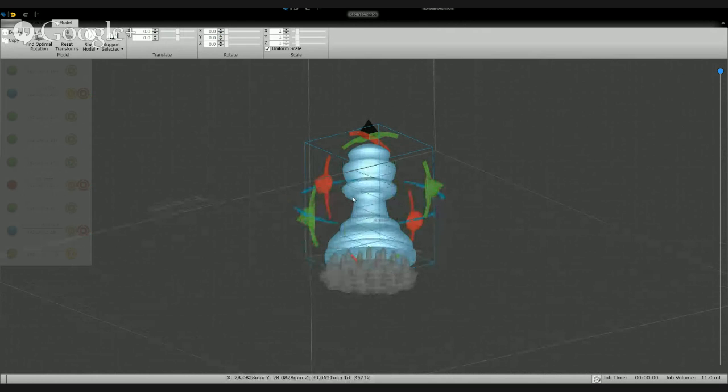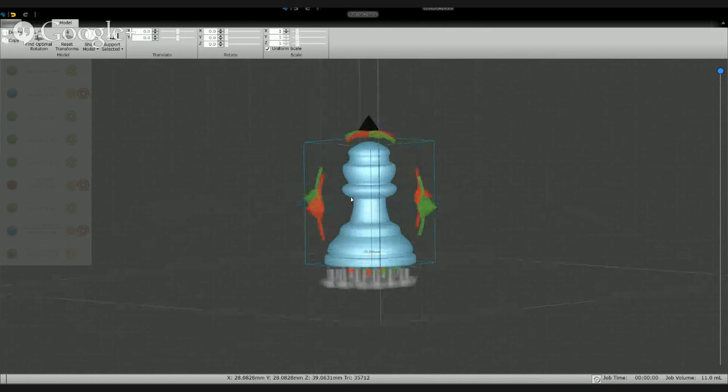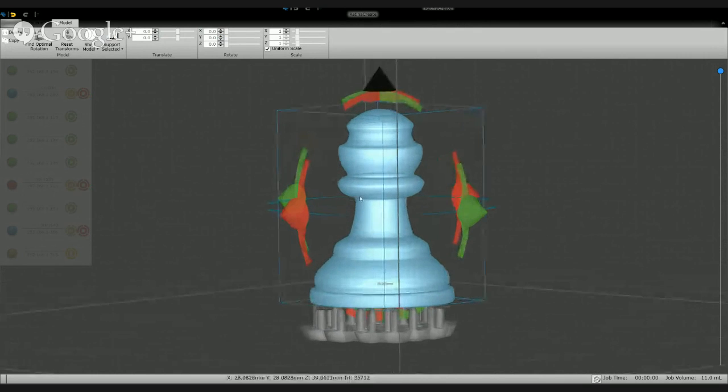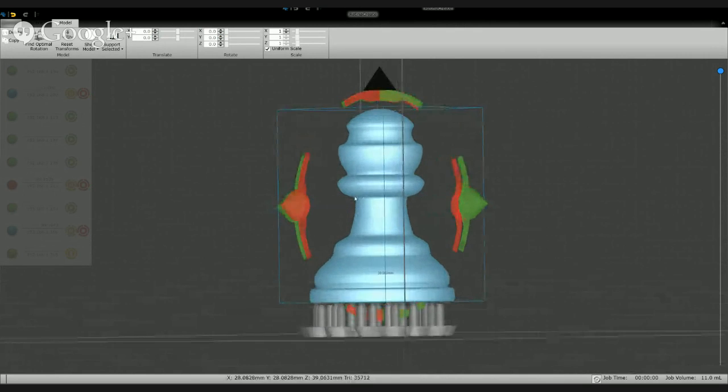You may get a slight amount of pull upwards. So if you were to somehow measure the height from here to here with some sort of tool, it might be off by a couple hundred microns because of the suction force during the pull when it's unsupported on these horizontal things. But it'll be a very small error.